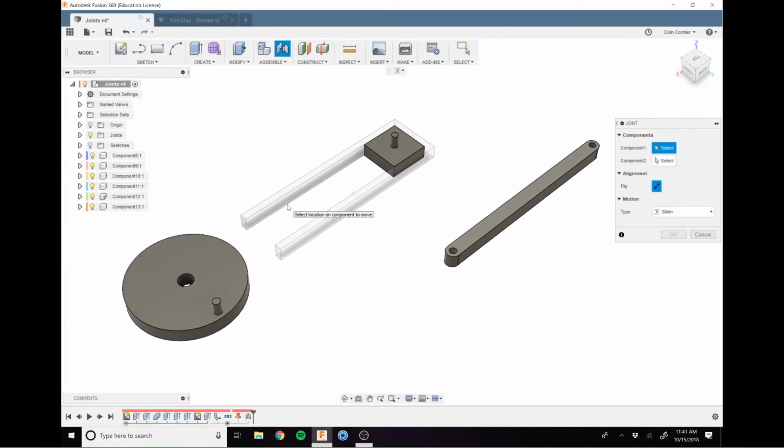I use the joint tool because you can still use it even if bodies and components weren't sketched in relation to each other. An example of that is this linkage here. If I wanted to create all as-built joints for this assembly, I could. I'd have to sketch this linkage in place over this pin and then over the other pin over there, and then create the as-built joint.